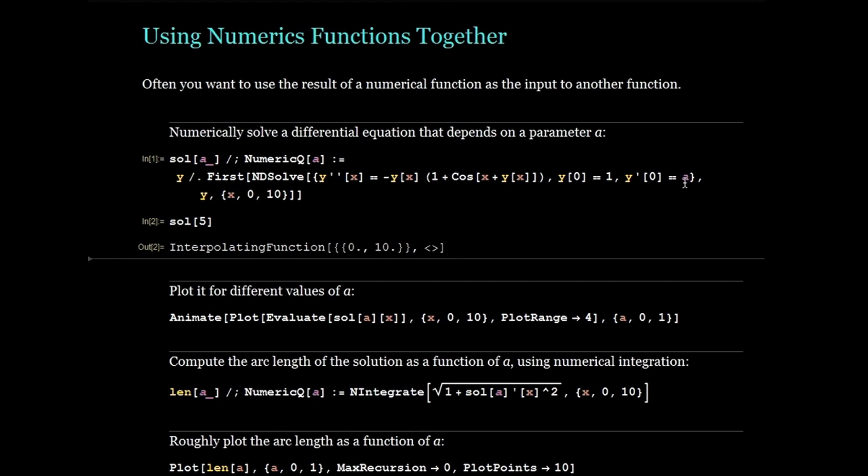The most important thing to note about this function is that its definition is only meaningful when a has a specific numerical value, and not when a is an abstract symbol. You express this by attaching a condition to the definition of the function. This is often useful to avoid Mathematica emitting some warning messages later on. Once you've defined a function sol in this way, you can use it like any other function. Here's an animated plot of the solution to this differential equation as a ranges from 0 to 1.